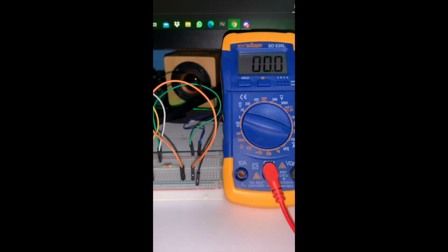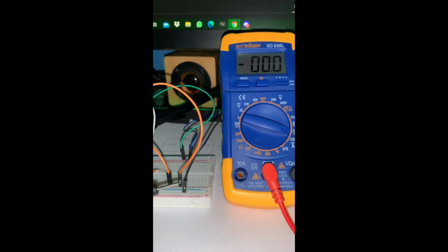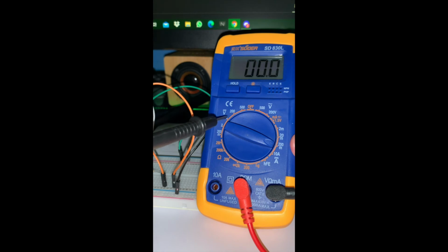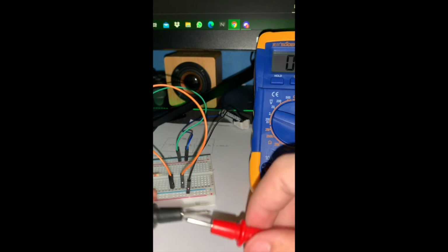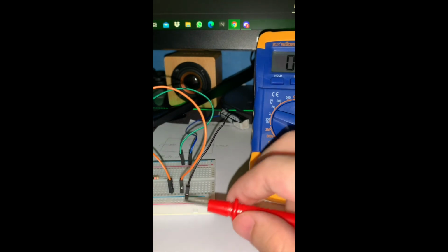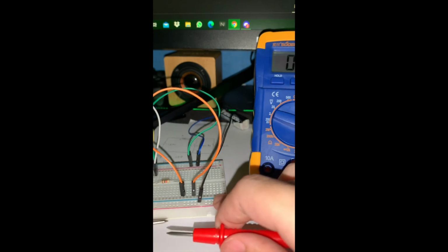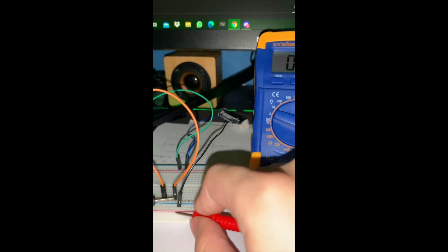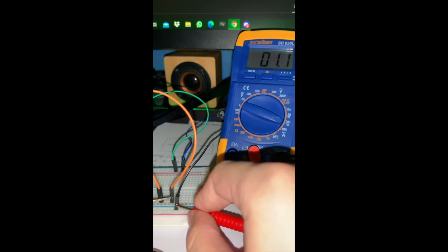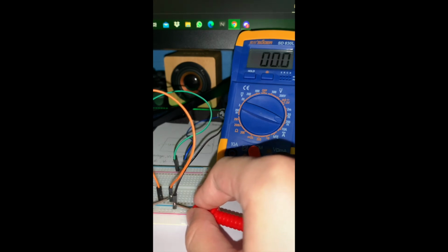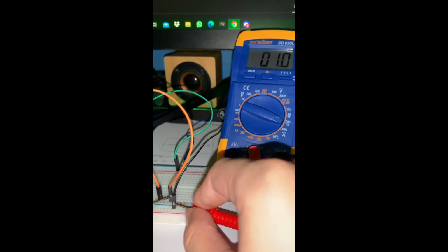To measure the total current of this circuit, firstly we change the mode of the multimeter from voltage to ampere, and then to find the total current of the whole circuit, we break the circuit first and rearrange it, and then we can calculate the total current. We can measure the total current, which I'll get 0.10